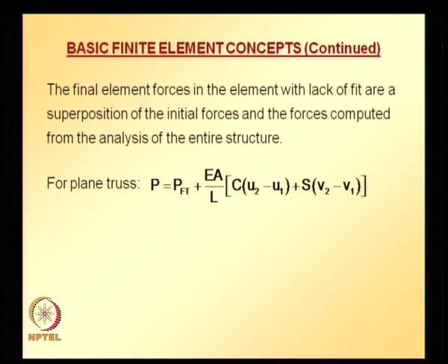For plane truss problems, the equation looks like this. The first term Pft is nothing but the force that is required to stretch or compress a member to force fit it into the given structure. This is for plane truss, but the rest of the analysis proceeds in a similar manner as we already looked at in the last class.